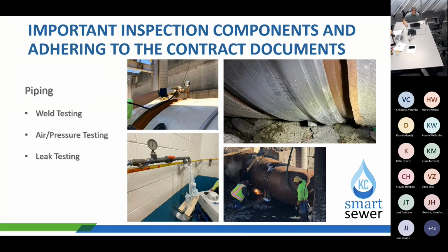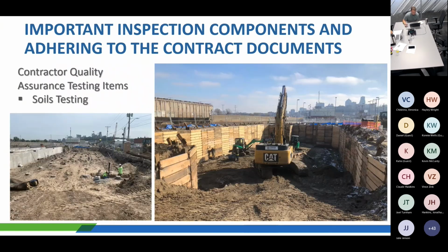So think about that as we go through some of these. So for the soils testing, you want to jump back real quick. I'll try to go through these relatively quickly because I know we're running a little bit long. Getting proctors tests out there, understanding what's needed in the specs related to soils, whether it be underground piping and bedding materials, subsurface preparation, testing, and then backfill testing as structures start to come out of the ground. Those are all pretty common elements to a lot of these facilities projects that we look at.